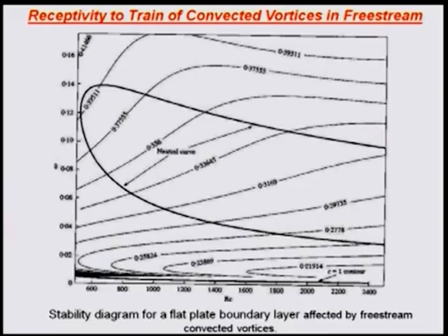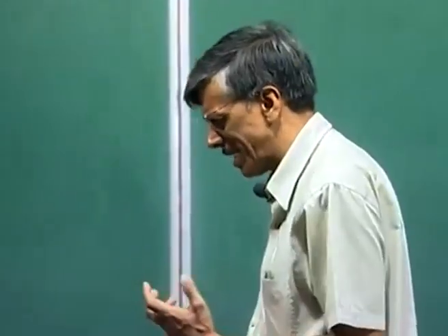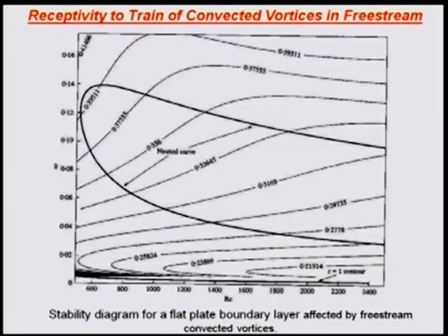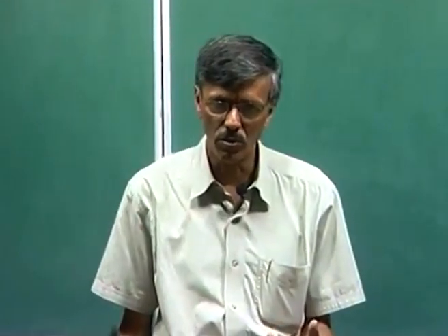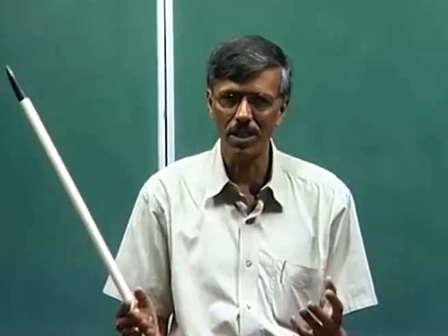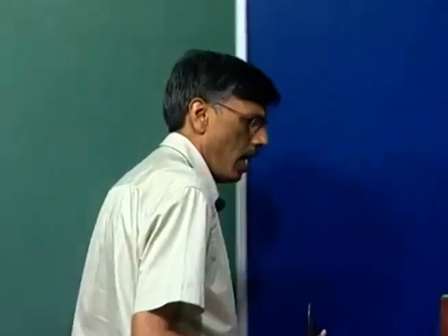So this particular route of creating instability by viscous vortices moving in the free stream is a very potent one. And since this creates wave packets and not a wave, we went with the crowd and called it a bypass mode, but the constituents are still the Tollmien-Schlichting waves. So we are getting a wave packet constituting of many TS waves. That's what we should be looking at, and what we do is we go ahead with the calculation.